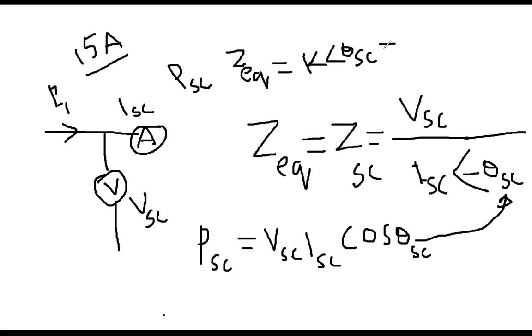This means it has two components: R equivalent plus jX equivalent. Everybody say, this is in polar form. This is a phasor, this is a vector, and this is Z equivalent. From here I got this one. Now you convert into rectangular form. In the rectangular form, the first part is the real part, R equivalent, and the second part is the imaginary part, jX equivalent.